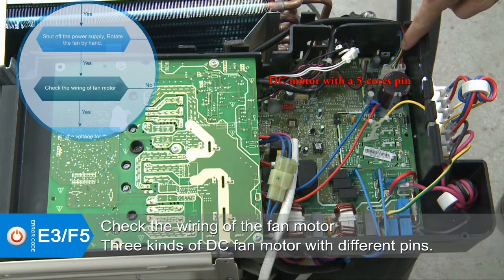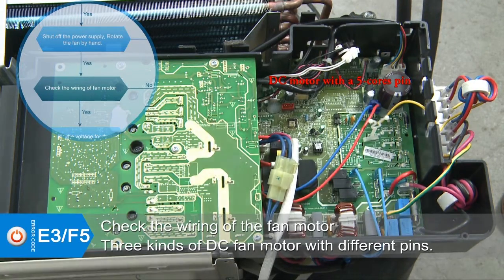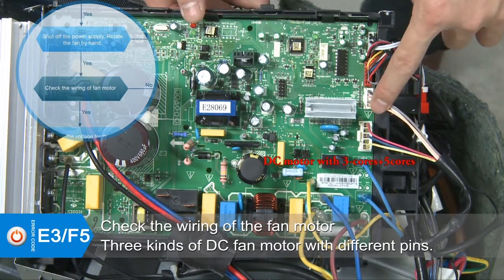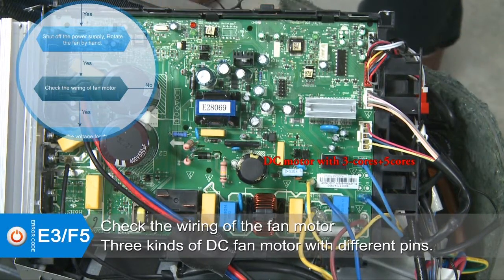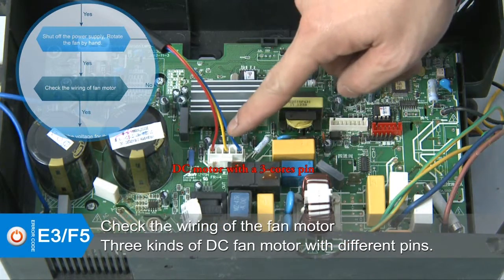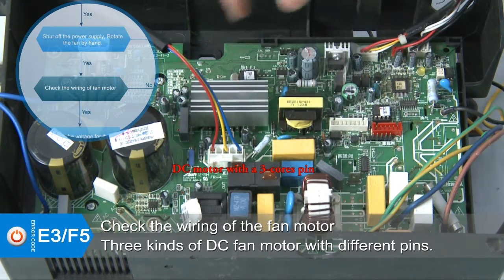First, DC motor with a 5 cores pin, which has a control chip inside itself. Second, DC motor with 2 pins, 3 cores pin and 5 cores pin. The control chip for it is on the main PCB board. Separately, the 3 cores pin connects to the power supply, and the 5 cores pin is used for signal transmission. The third, DC motor with a 3 cores pin, which has the control chip in itself.